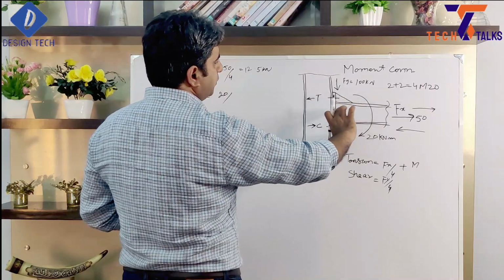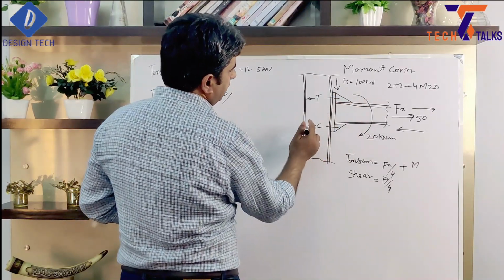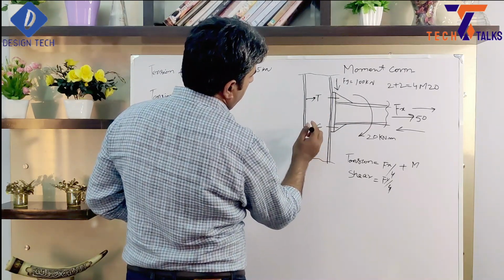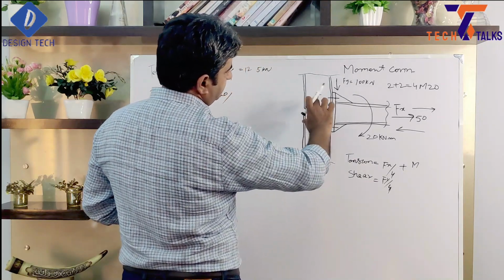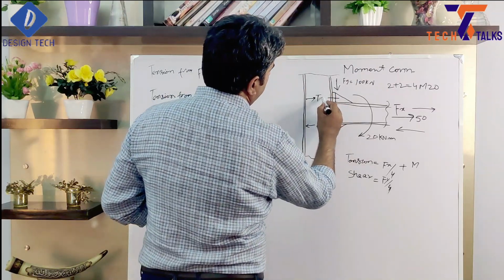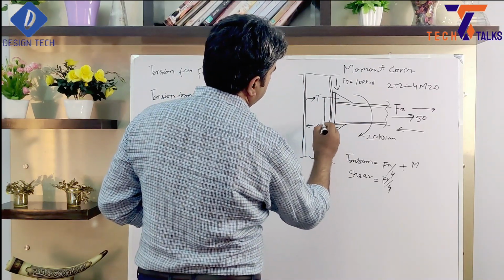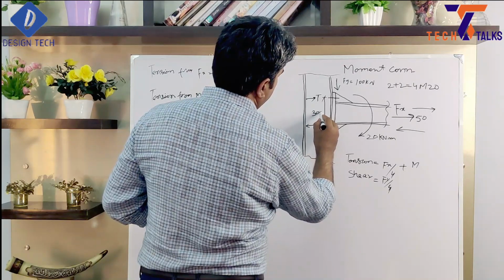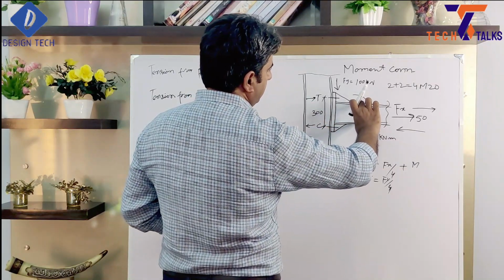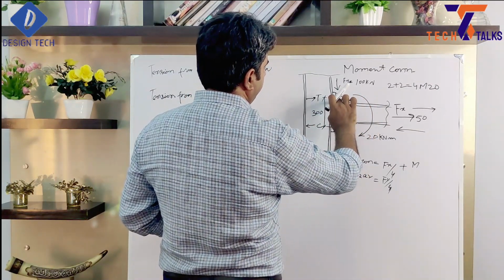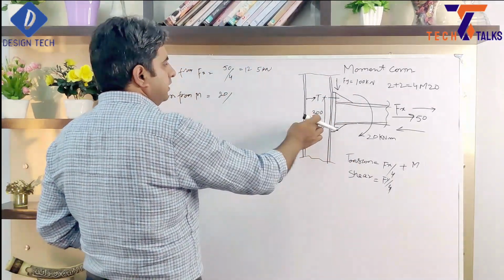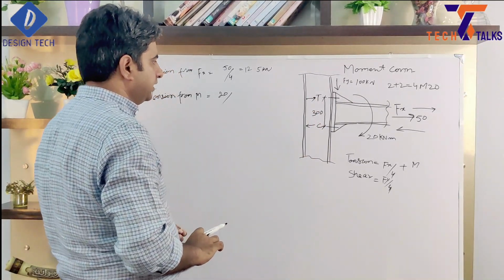So when there will be pull and push, it will be on these bolts like this. If this is our tension, then here will be compression. So pull and push depends on this distance. Suppose this distance is 300, because it depends on how much our member size is, and 50 or 60 we need to provide here. So we consider 300 for example for our calculation.